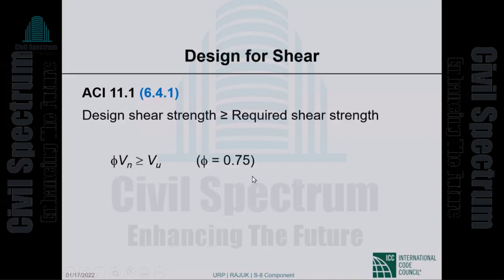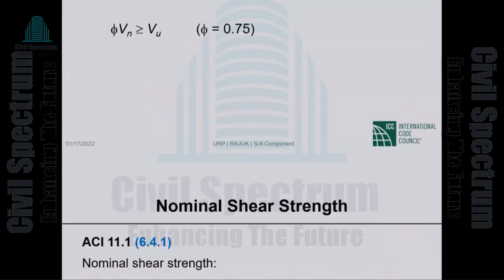In shear design of ACI 318 and BNBC 2020, phi for shear is 0.75. There are exceptions to that, which we may come across as I take you through other stuff, but normally, unless something specific is said, phi is 0.75.